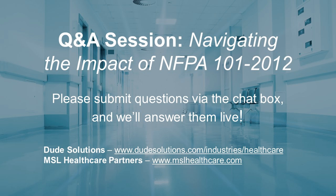As you may know, hospital grade receptacles are required in patient care areas only if you don't want to test your receptacles on an annual basis. You're not required to have hospital grade receptacles in patient care areas, but if you don't, then you have to test your receptacles every 12 months. If you have hospital grade, then that's not required.